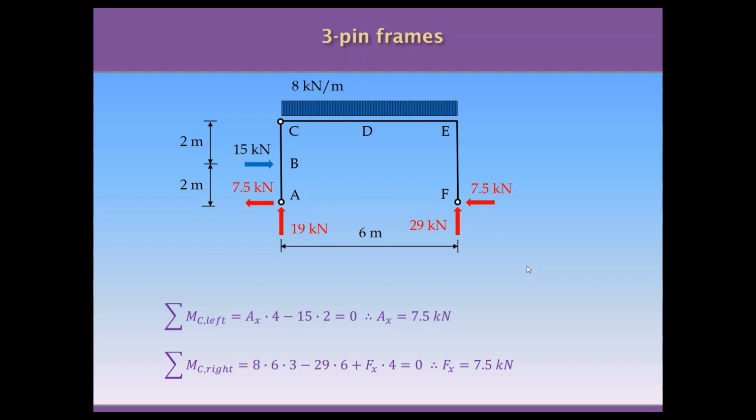So in this way, using these additional two equations that this hinge has allowed us to write, we are able to resolve the structure in terms of reactions. But again, this is only possible because this structure is isostatic. If we have a hyperstatic structure, we will need to use extra equations, virtual principle of forces or displacements or something like this.